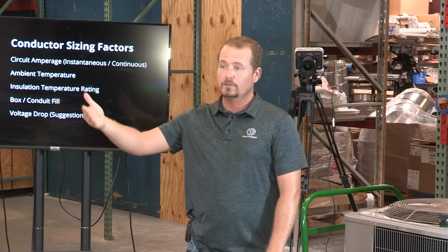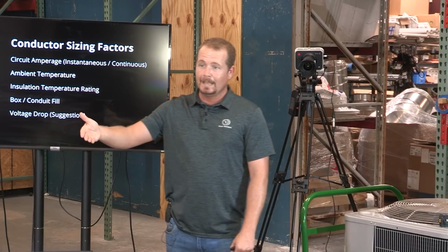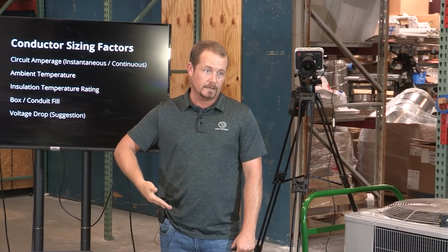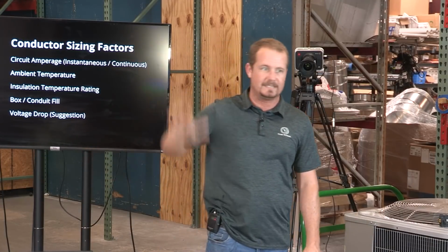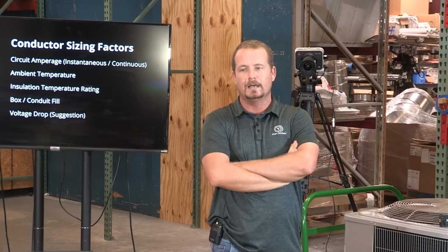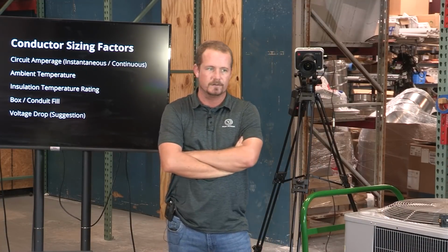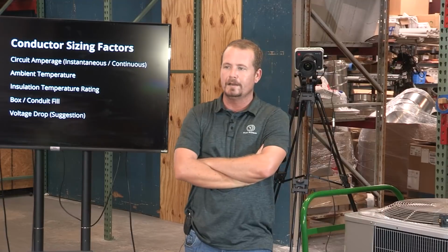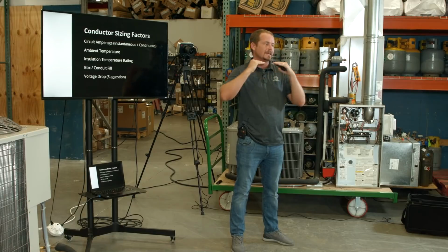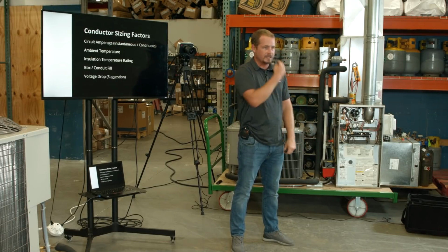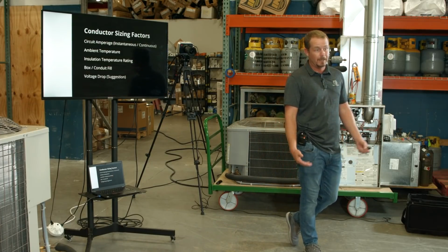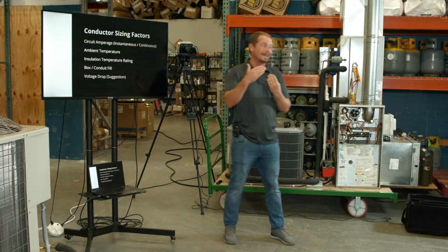So as an example, with a residential AC system, it's going to be very difficult for us to deliver a voltage that's too low. A lot of people, it can happen in a brownout condition where there's a significant drop, but under normal circumstances, it's going to be really abnormal that we drop low enough, because most of our single-phase air conditioning systems are rated for 240 volts or 230 volts or 208. Right? That means they're designed to run at 208 under normal conditions, because they're designed to work on two phases of a Y commercial three-phase power supply. So they're rated all the way down to 197.